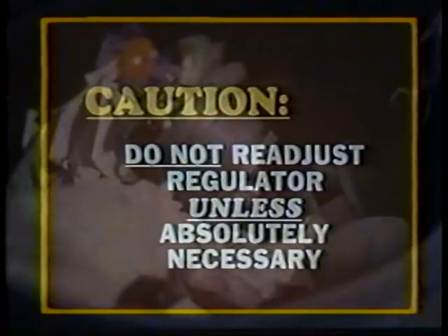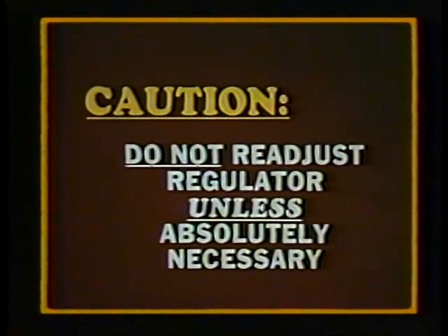If a regulator adjustment to correct a pressure drop is made improperly, or an adjustment made when the real problem is due to obstructed airflow, the pump will be unnecessarily overworked and its life will be shortened. In modern pneumatic systems, both the vacuum and pressure regulators are quiet operating and trouble-free. Once they've been set, do not readjust them unless absolutely certain the regulator is at fault.